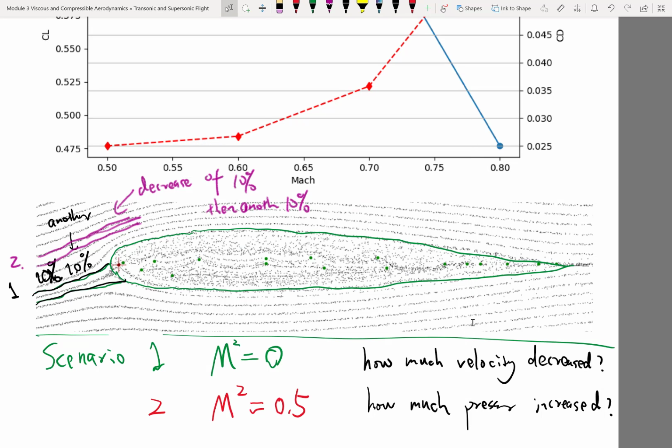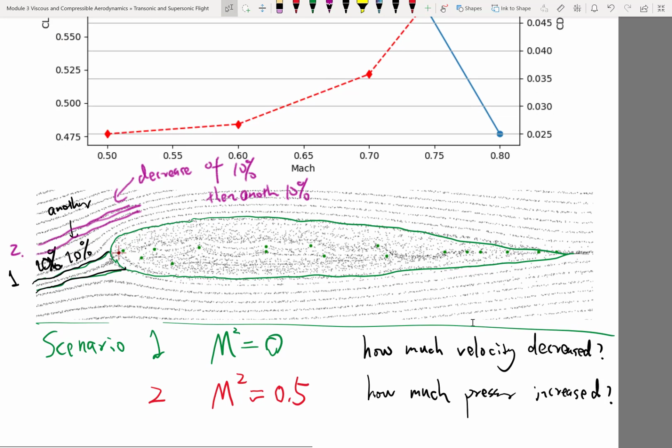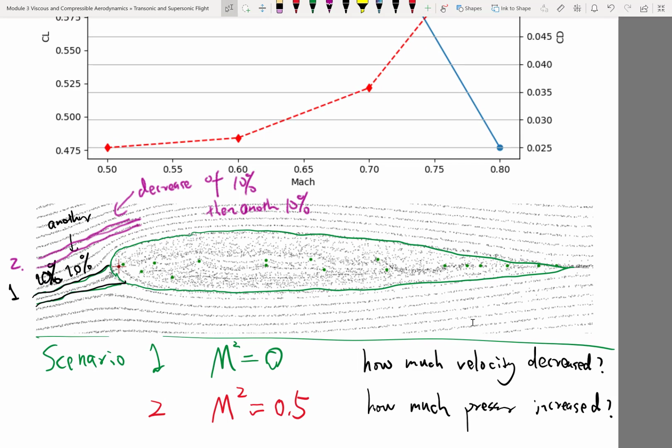All right, I think most people are done or are at least getting towards your conclusion, right? So can we conclude some intuitions or results, some things you can generalize from this analysis? First of all, when we are looking at velocity increase or decrease, does the incompressible case or the compressible case have a stronger response of velocity with respect to a change in the stream tube area?